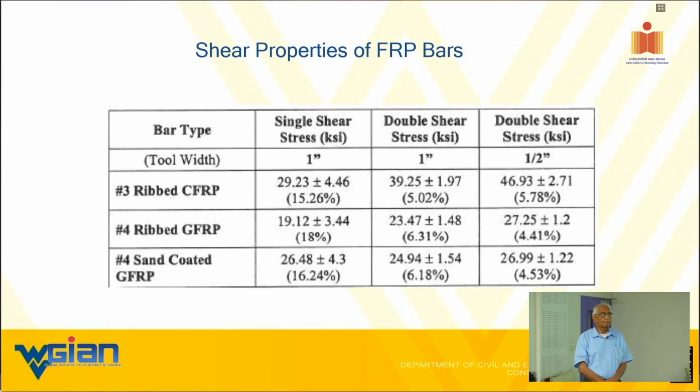Okay, wait. That's a broad statement. The shear I'm talking about is Timoshenko shear. I'm assuming you know some of that. I can write an equation in a minute. So, say I have a bending stress, and bending stress means MC over I. Correspondingly, I have a deflection, PL cubed over 48EI, that kind of a thing. Okay, that's one part. Then correspondingly, I also have a shear stress and a shear deformation.